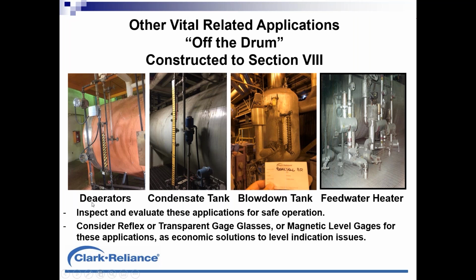These include deaerators, condensate tanks, blowdown tanks, and feed water heaters. While these are not Section 1 because they're not fired vessels, they're Section 8 vessels. Some of the rules are a little different, but many times we'll find users adopting Section 1 rules for level instruments because there's no clear definition for instrument requirements within Section 8.